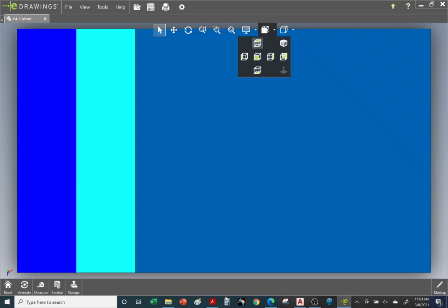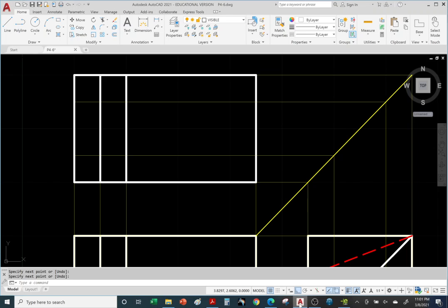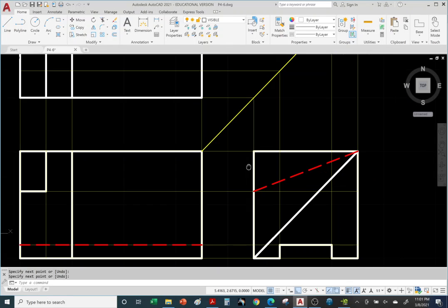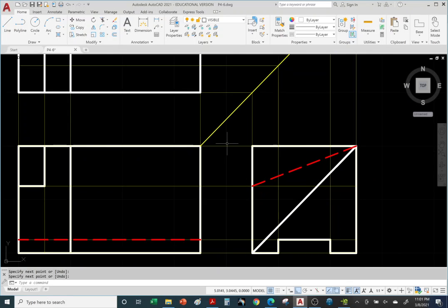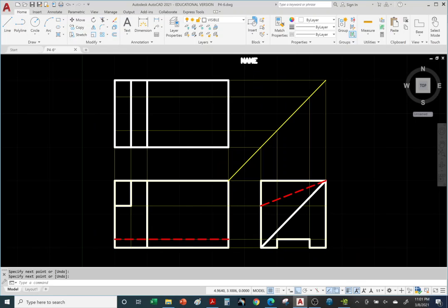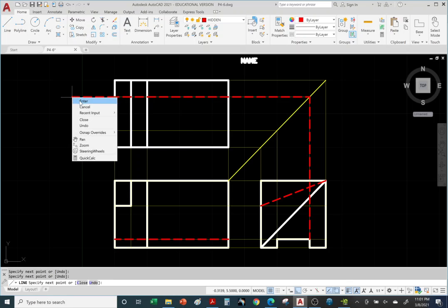Okay, so let's go back. All right, so we're going to use the right side view to help us create those red hidden lines. So let's go to the red hidden layer, use the line command, and from the tunnel opening, let's start with the right corner. We'll go straight up, hit the 45, go across, right click enter.